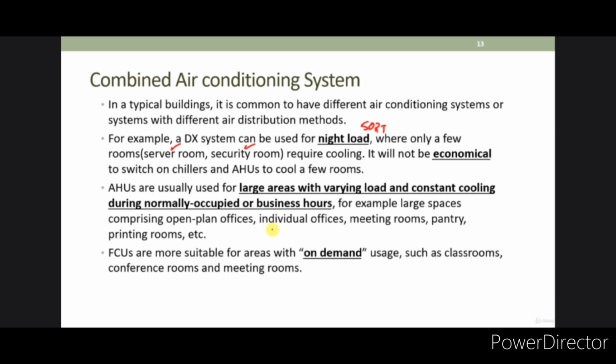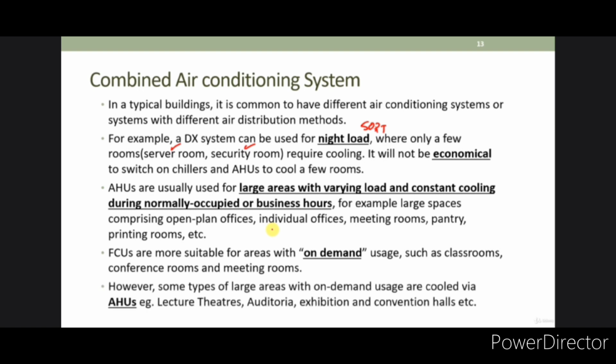Or when somebody books the room, then the facility management team may help to schedule it to switch on and off. That will save much more energy rather than having an AHU that always serves cold air into the room even when nobody is using it. But of course, for larger areas, sometimes even for on-demand usage such as lecture theaters or exhibition halls, it can be served by AHUs also.